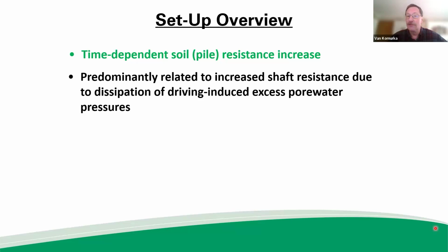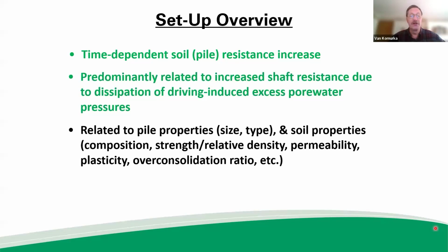There are other mechanisms involved. We won't get into that, but if you think of it in broad, general, most common terms, it's related to dissipation of excess pore pressures that are developed during driving. It's a very complex phenomenon. It's related to the pile, and it's related to a whole host of soil properties. I've even come to believe it's related to how the pile is driven, whether it's driven with a large hammer and large sets per blow or a small hammer and small sets per blow.